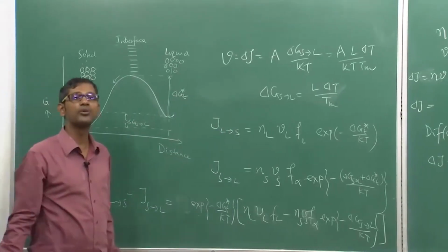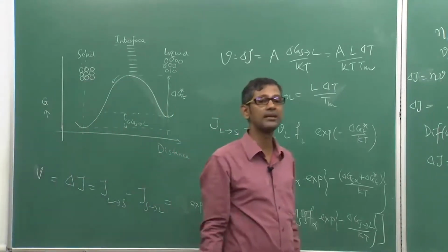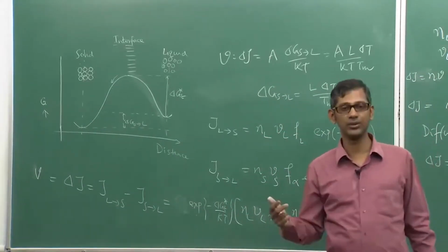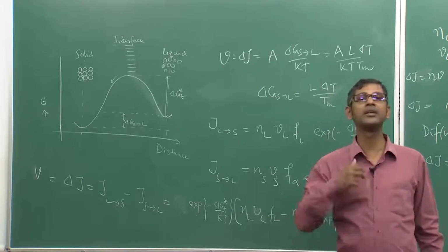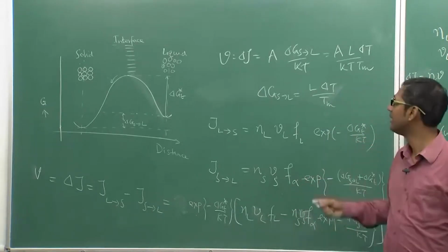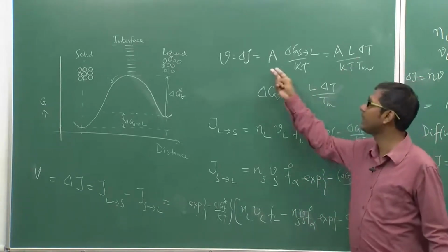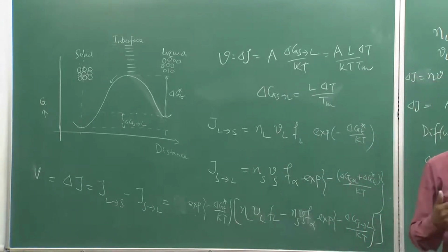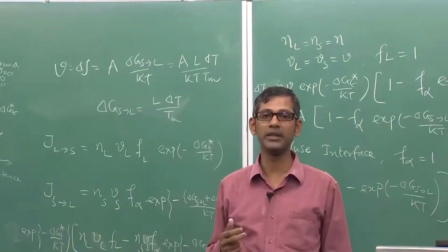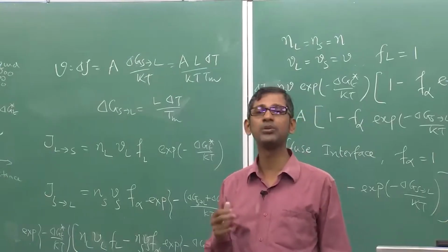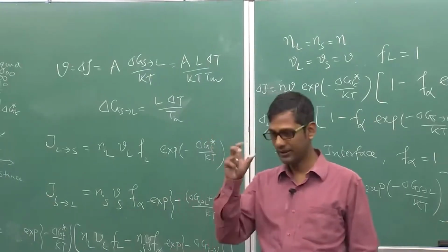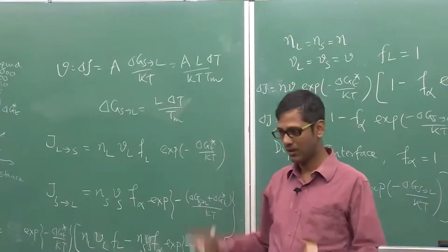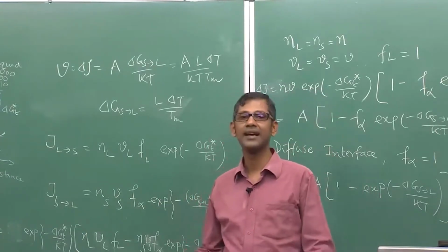And this kind of growth is known as continuous growth in the literature, where atoms will keep on jumping and attaching to the solid surface. From the liquid they will jump, attach directly to the solid, and the higher the undercooling, the higher is the velocity. This is only possible in pure metals normally. Let me tell you, pure metals, and a few pure ceramic solids, where in a ceramic solid each molecule can easily jump as an object, as basically an entity, and attach to the solid.